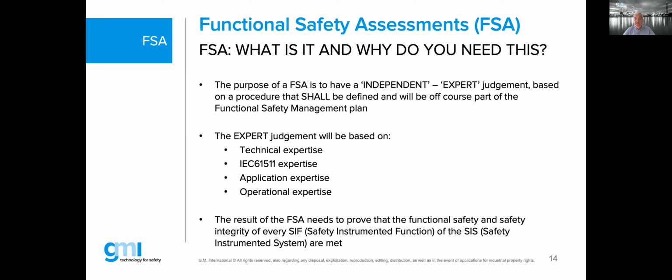Very shortly, any supplier of a product or a service shall have a functional safety management scheme in place and prove how adequate they are using it. And that's, of course, a real strong statement. And in that FSM, the functional safety assessments will be described. Expert judgment will be based, of course, on technical expertise, on the 61511 expertise, application, operational expertise, etc.